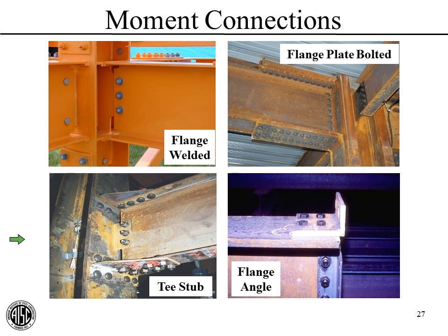Well, I'm going to assume that the participant is referring to a case like this, where we have the connection into the weak axis of the column, the minor axis of the column. And absolutely, you can certainly have a moment connection to the minor axis that puts the column in minor axis bending. In this case, we weld the flanges of the beam to the stiffener at the top here and at the bottom there.